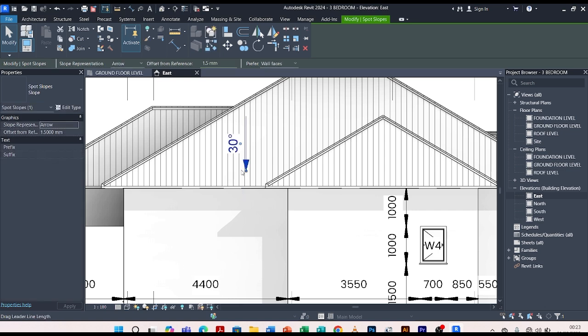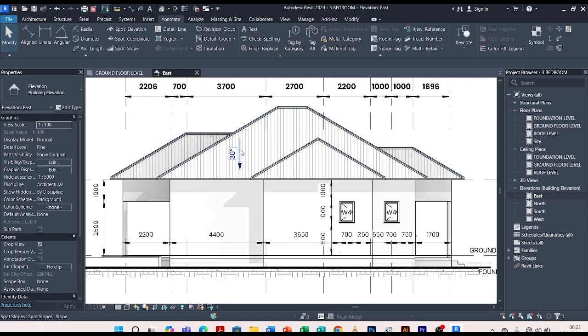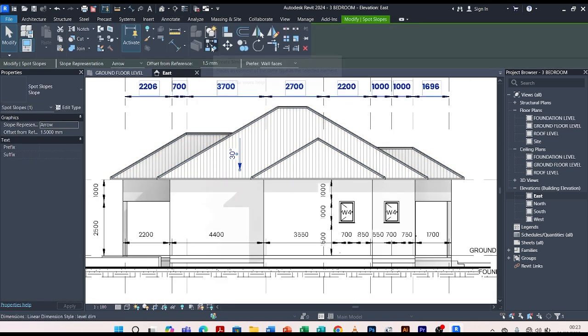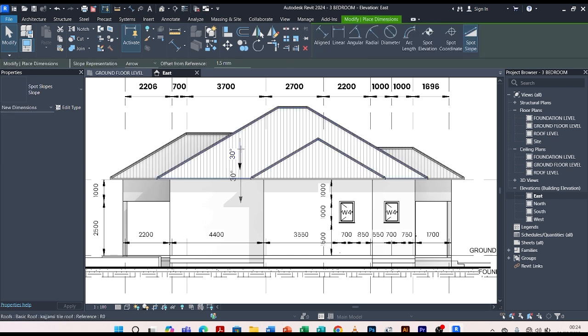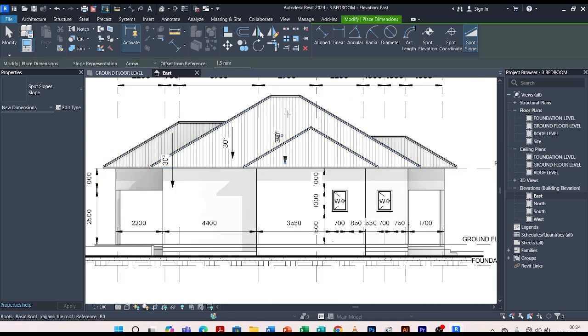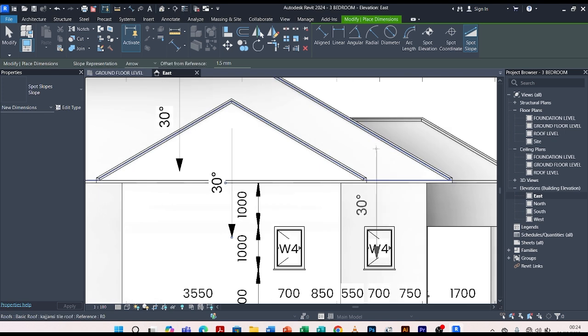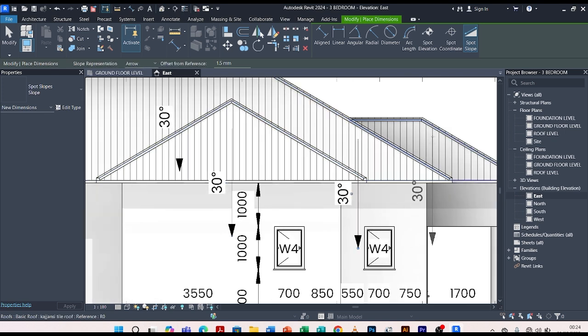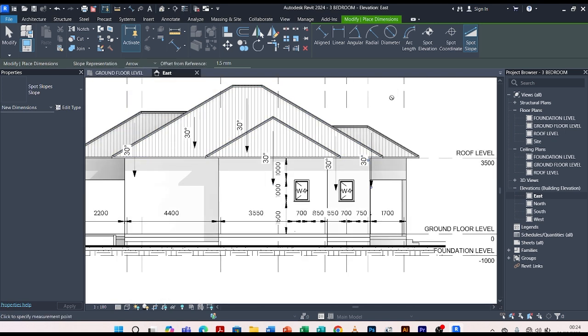So you can adjust this, then you can do the same. You can click on it, then you come here and create similar. Or you type CS on the keyboard. That means we are going to create similar parameters of this degree. So I can type CS on the keyboard, then I keep marking off my slopes. So I'll go on by adjusting them. Can have something like that.